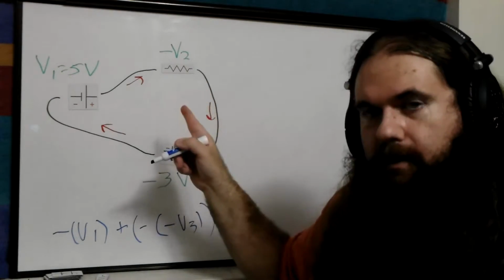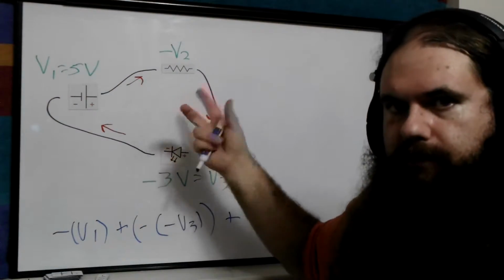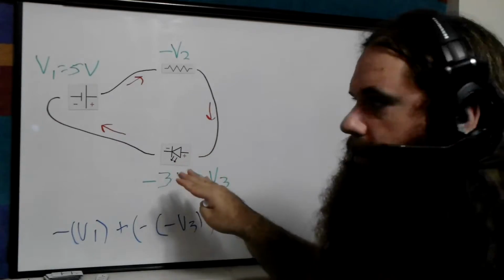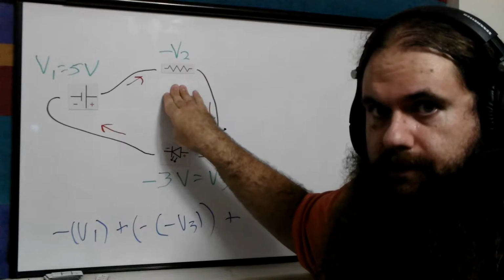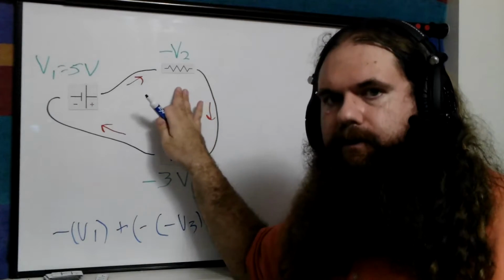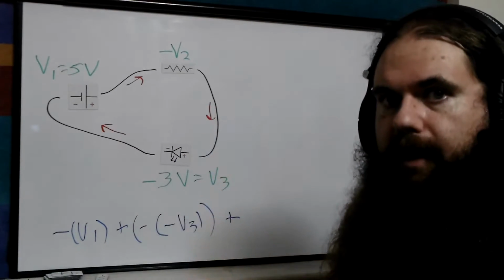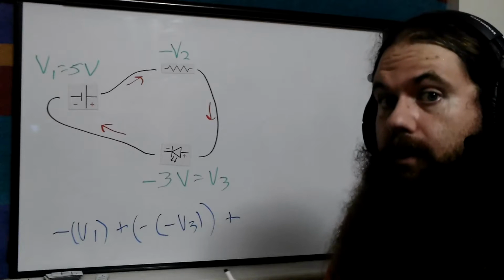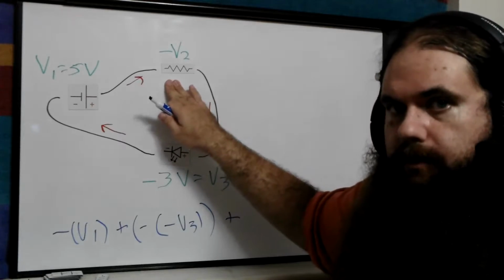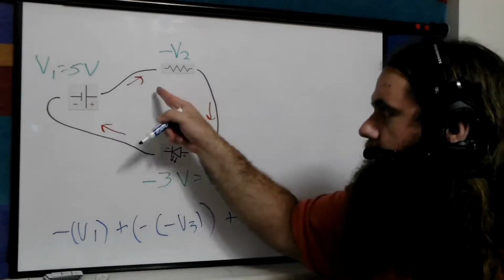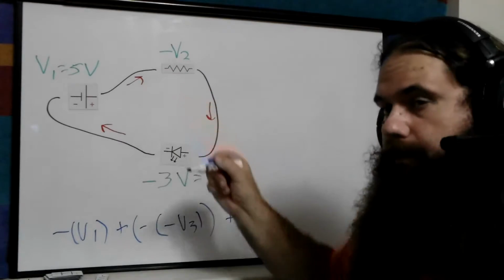Now, a resistor is going to drop voltage no matter which direction you go. If we actually reverse the current and take the LED out because it's going to block the current, but pretend the current flows in the other direction, you'll still get the same voltage drop. But this is for circuit analysis. We're not actually flipping the current. We're just drawing it backwards because we can. There are situations where you want to do this. Uncommon ones, but they exist. So you can go across it, but we're going backwards. It's the arrows. The current arrows we've drawn determine if we're going backwards.